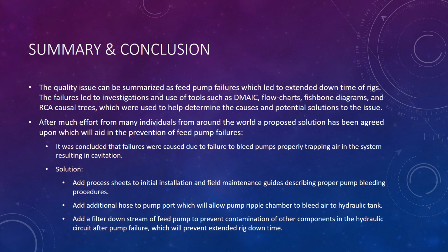So after a lot of effort from a handful of different individuals around the world, we were able to propose a solution to prevent the feed pump failures. It was concluded that the failures were caused by failure to bleed the pumps properly, which trapped air in the system and resulted in cavitation.